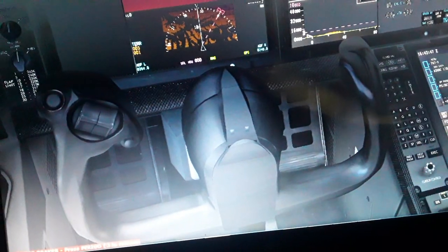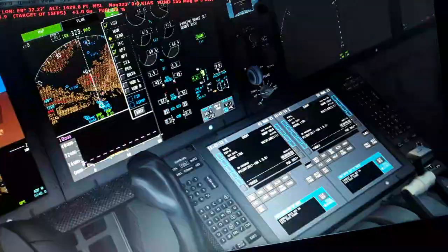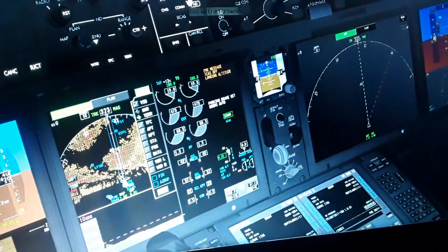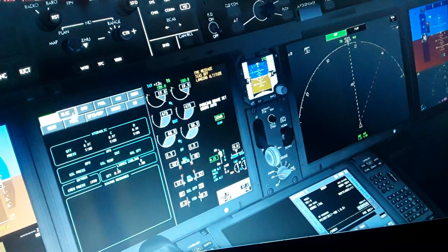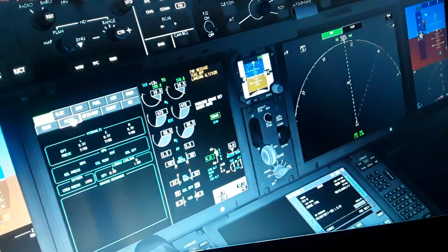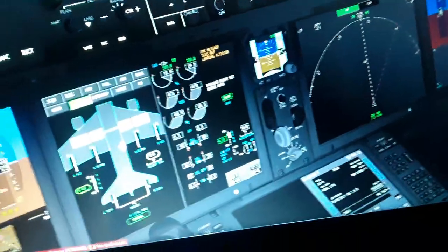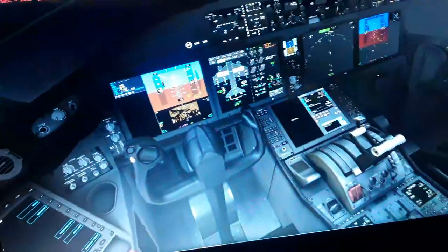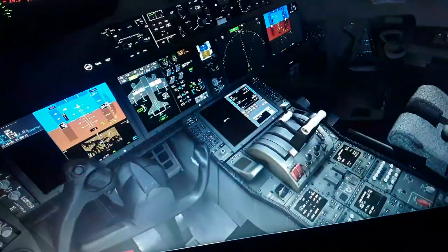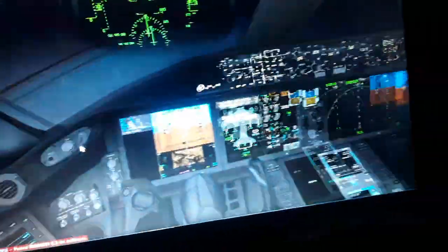The horizontal trim stabilizer over here, this is for the horizontal tail of the aircraft. You can trim up and down, and you can see the degrees in the Boeing 777 somewhere. Here, maybe here you can see it in the info, CDU, systems. So we have the systems, the flight controls. I'm gonna see here the elevator, the position of the elevator. So you can see we use this to move around the flight controls like this, and you can see the flight controls are moving, having the display of the systems display.